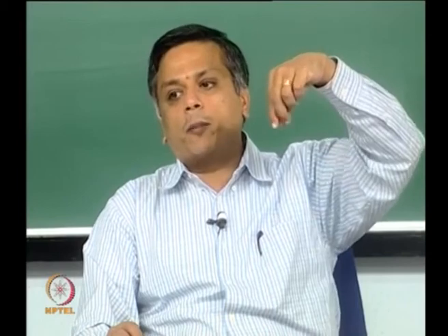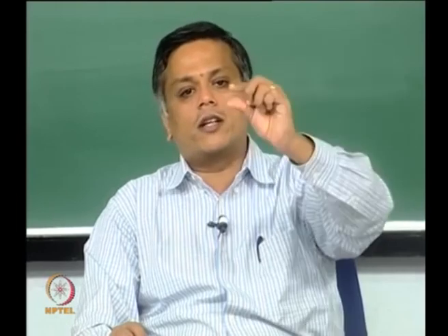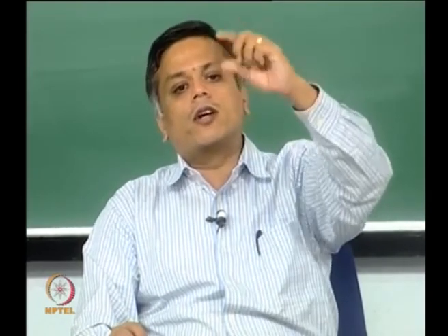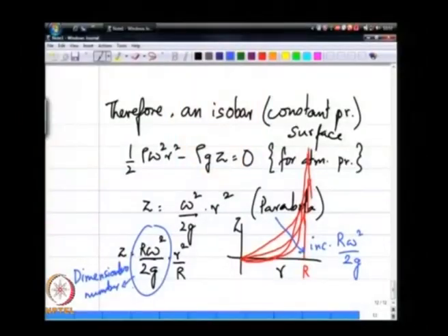So, the spray properties of this nozzle are independent of whether you are looking at the spray horizontally, vertically, or vertically upwards. It does not matter what the component of g is, you are going to get essentially what looks like the same spray. For that to happen, this r omega squared over 2g is a very large number.